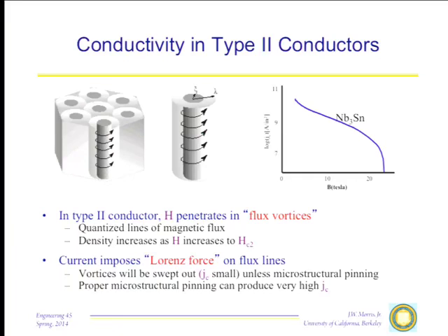So with a superconductor, granted, putting it well off the floor is not the best solution to this. There are much more sophisticated ways to do it that we know now. But to make a good superconductor, one that carries a lot of current, you don't want a clean material. You want a dirty material. You want to dirty it up in intentional ways, so you pin these vortices, make it very difficult for them to move, and in that way create a material that can carry current. For example, one of the best type 2 superconductors now is niobium-tin, which is widely used, and it has a critical current characteristic something like this, provided that it is made, as I'll show you in just a minute, in a way that provides lots of pinning sites for these vortices.